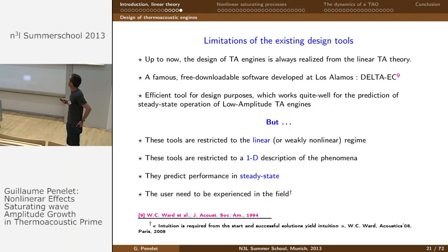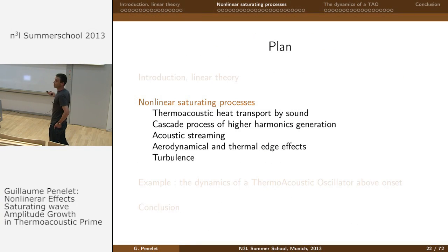And the problem with this linear theory is that it is limited to a linear description, so a low amplitude description of these engines. It is also a one-dimensional description of the phenomena, but it's not sure that the temperature distribution is only one-dimensional, and it only predicts the performance of the engine in a steady-state regime. So we need to discuss the nonlinear processes which are responsible for the saturation of the thermoacoustic instability.